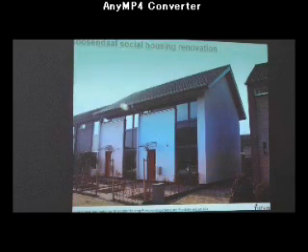From the picture, you can see the roof and the outer wall are obviously expanded from the existing building's roof and outer wall. This building envelope expanding is caused by the insulation addition to the roof and the exterior wall.